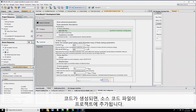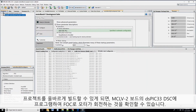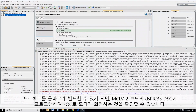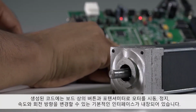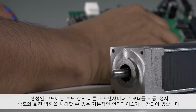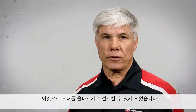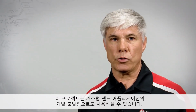Once the code generation is completed, the source code files get added into your project. After successfully building the project, program the dsPIC33 DSC on the MCLV2 board and see your motor spinning with FOC. The generated code has a basic interface to start, stop, and vary the motor speed and direction by pushing the respective button or turning the pot on the board. Now that you have successfully spun the motor, this project serves as a good starting point for developing your custom